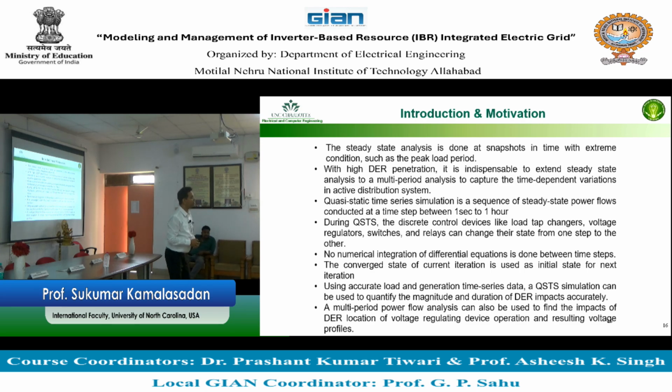So ideally, you have to do 8,760 times in a year, which means one time every 1 hour. That's what people say. Such a study is called an 8760 study. You can Google and search and you will see 8760 study. Which means every year the PV is changing, the load is changing. You can mix and match and run for every time.